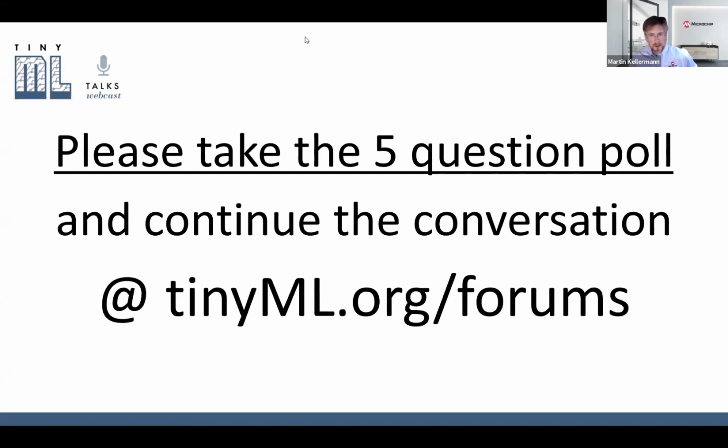Okay, thanks. Okay, we have got already quite a few more questions in. There's another question. What would be the gain if you would convert to VHDL without using the HLS tool? So in principle, HLS does convert here to Verilog, and then I'm taking the Verilog and bring that into the GUI interface as an IP core.